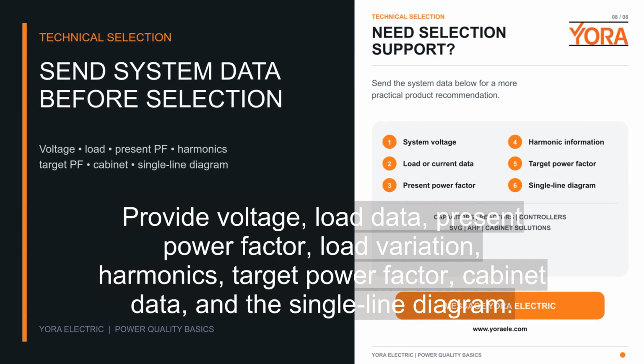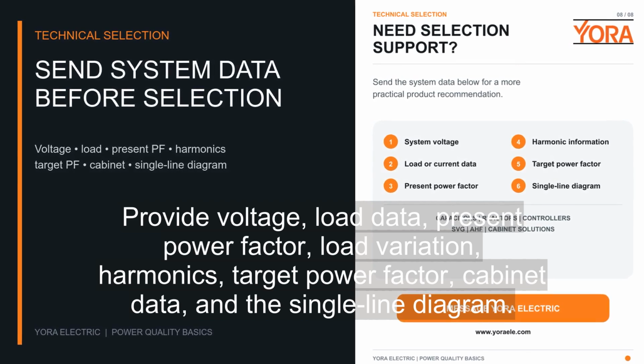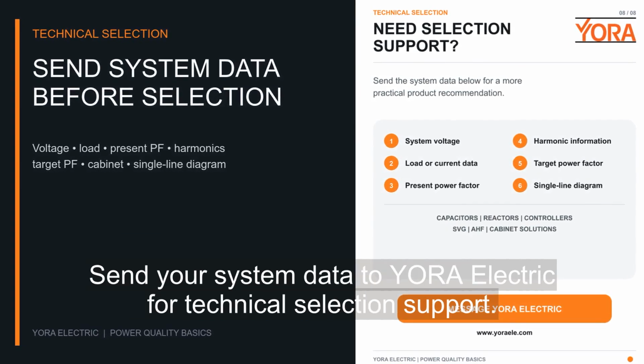Before selecting equipment, provide system voltage, load, or current data, present power factor, load variation, harmonic measurements, target power factor, cabinet information, and the single line diagram.